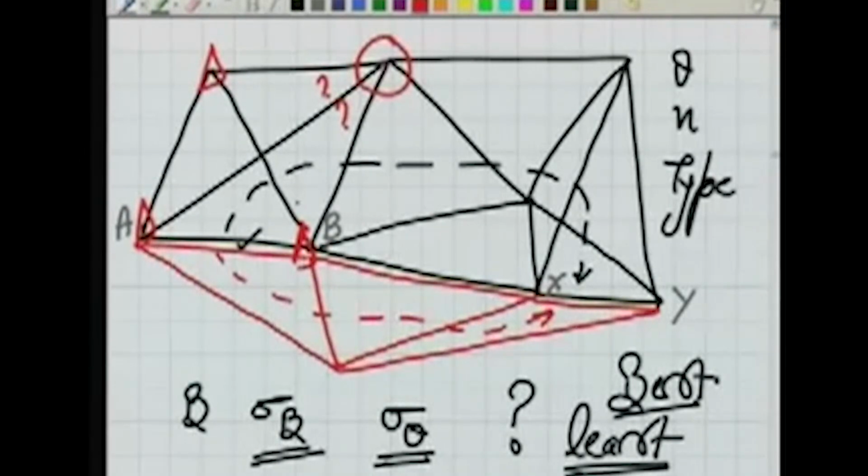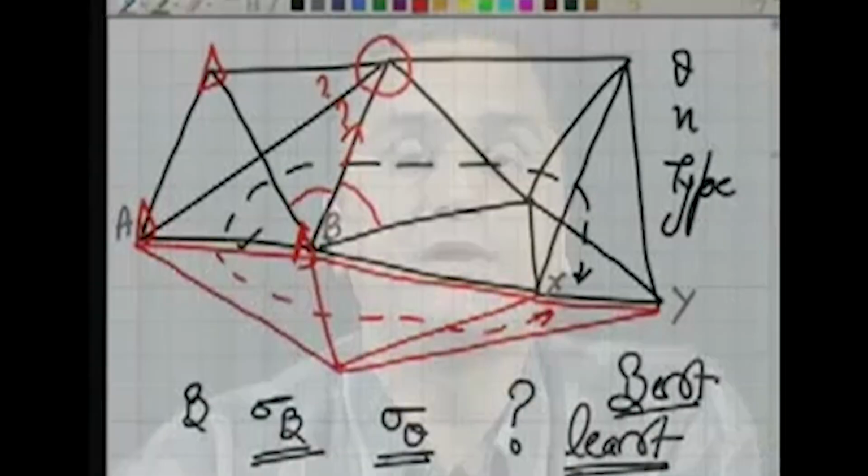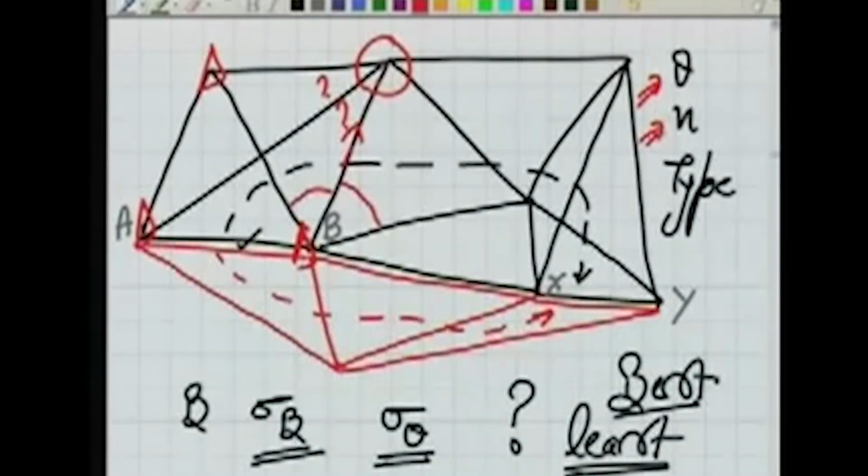Then, in order to measure, for example, the angle here and the angle here, this particular line has been bisected twice. Number one, in order to measure this angle, then to observe this angle. So wherever there are multiple observations like this, we should give more weight to that. So what do we end up with? How many angles, how many triangles, how many lines, what are the types of the angles, the sizes of the angles, all these things need to be put together in a formulation, and that formula should be able to give us the strength of the figure.